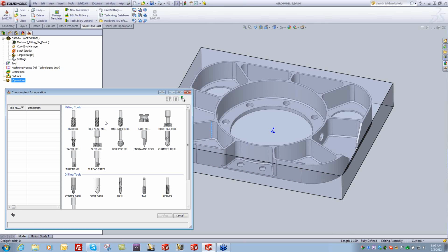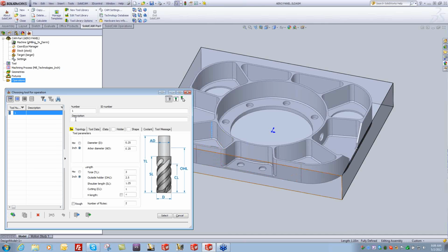I'm going to go ahead and grab, I guess, an end mill for the outside. And we'll call it a 1/2 inch. Now down here we only have a 1 inch cut length. This very much matters because iMachining will not take it any further than what the cut length will be. So if this is over an inch, it'll have to be done in 2 steps if you don't have the cutting length. So I want to make sure I can do all of it.